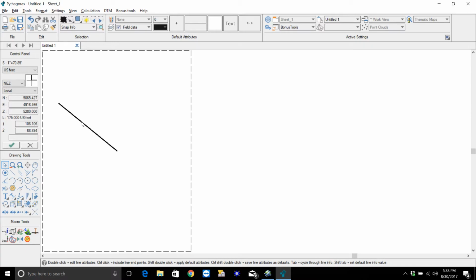So what I've also got now is when I hover over that line, you notice I've got the coordinates. Or let's just say that I go up here and click on the end point. Now there are the coordinates of that particular point. So we've set a line now based on a bearing and a distance. Let's do one more. I'm going to click the line tool.